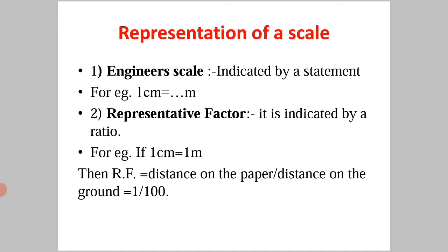The next point, we will see the representation of a scale. In surveying, engineer's scales are indicated by a statement, for example 1 centimeter is equal to 1 meter, meaning convert to meter. The representative factor is indicated by a ratio.